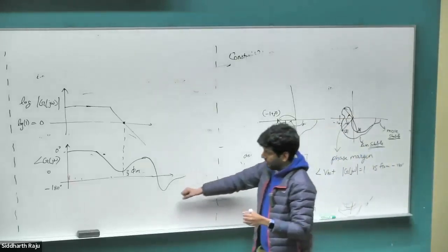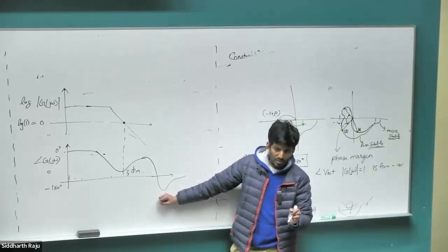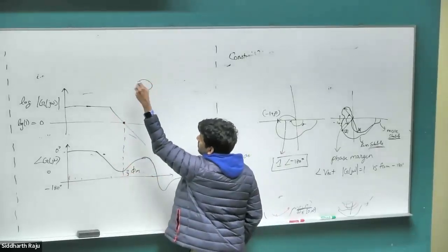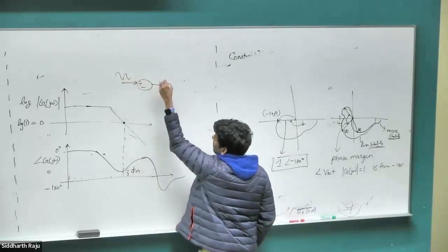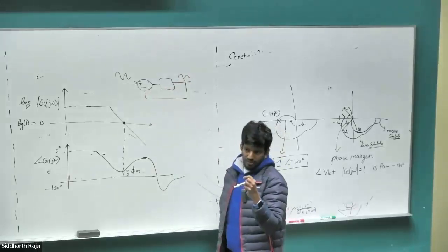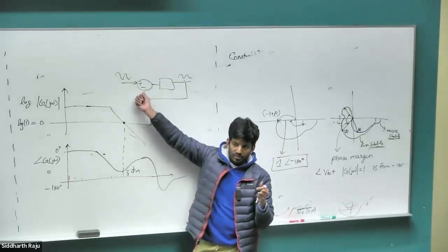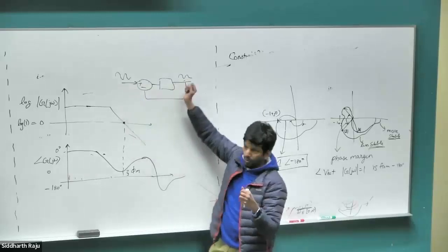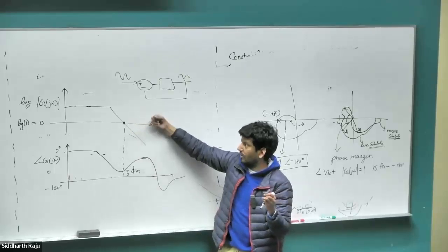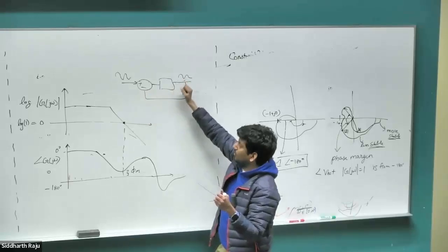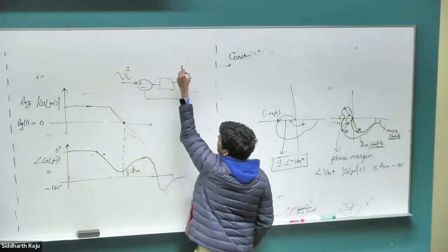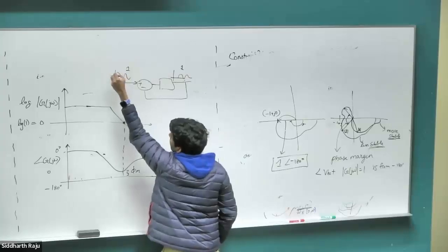So far out we can have a phase shift greater than 180 degrees and it should be fine, our system will survive. Because the idea is, if the signals are behind, what does the phase margin of 180 degrees mean? If I give some signal input, let's say a sine wave, and this transfer function does something and creates some other sine wave, if the sine wave is 180 degrees phase shifted, that means this negative becomes a positive in effect. It's the same as taking the signal and adding it to itself, and then going as output, then coming back, adding to itself, adding to itself again. That's what instability effectively is, right? But if that magnitude is collapsing a lot, fine. If you start out with 1 volt and you get 1 volt, which is also phase shifted by 90 degrees, then we are in quite a bit of trouble.